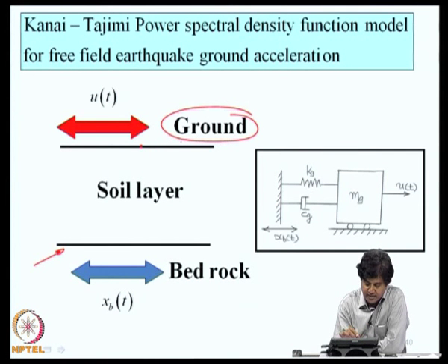Before the construction of any structure, if you study the ground motion, we call it free field ground motion, in the sense that no engineering structure is yet constructed there. So, most codes of practice define this free field motion in some manner. Conceptually, to make a model for free field ground motion, one model was proposed by Kanai and Tajimi. In this model, it is assumed that at the bedrock level the ground acceleration is a white noise, and